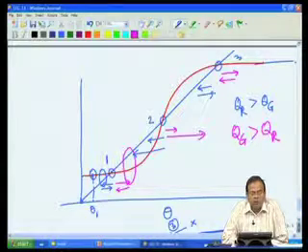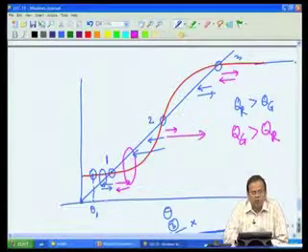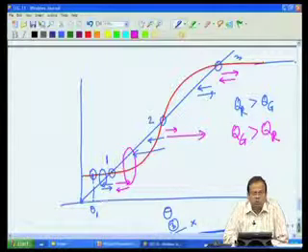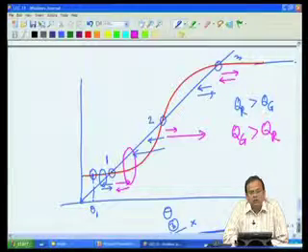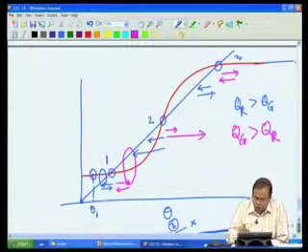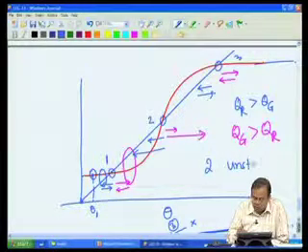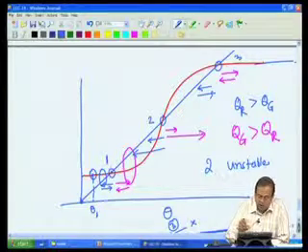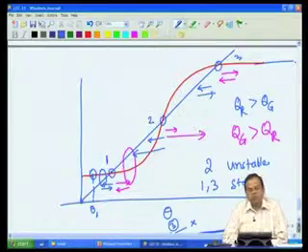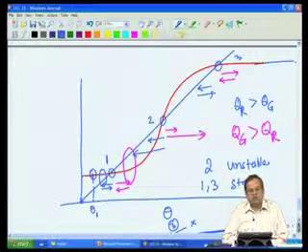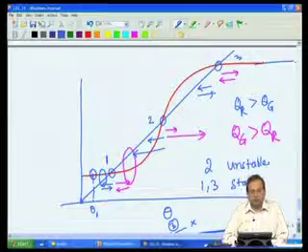In short, any perturbation at steady state number 2 is not going to die down, it is in fact going to amplify. We call such steady states inherently unstable steady states. So, we have steady state 2 is unstable and steady states 1 and 3 are stable steady states. We will look at the formal definitions and how we do this analysis in our next session.